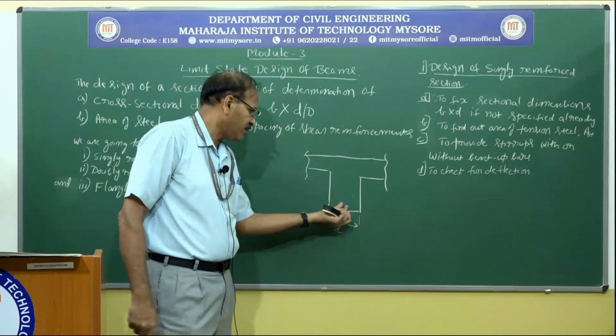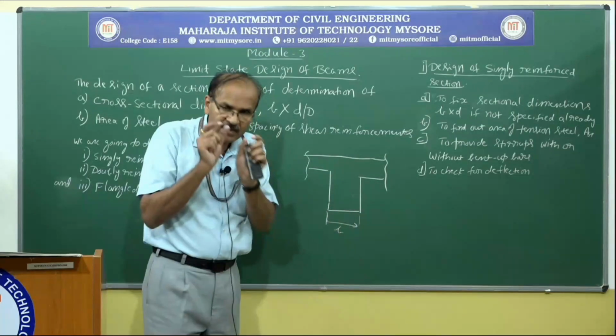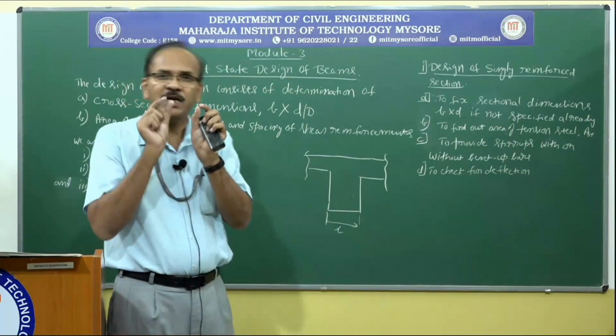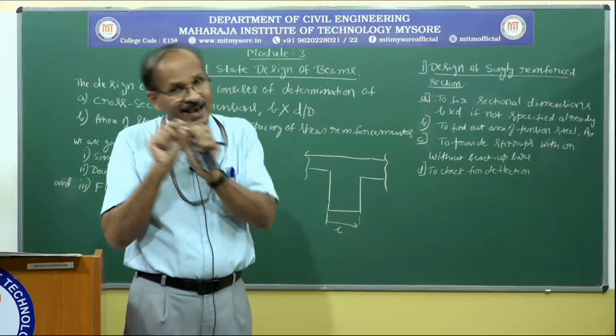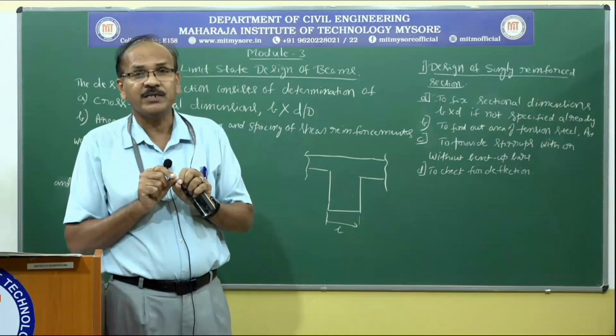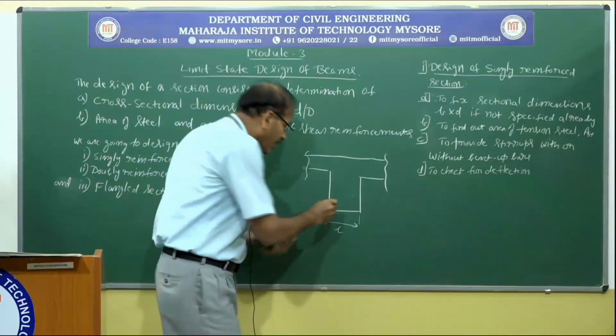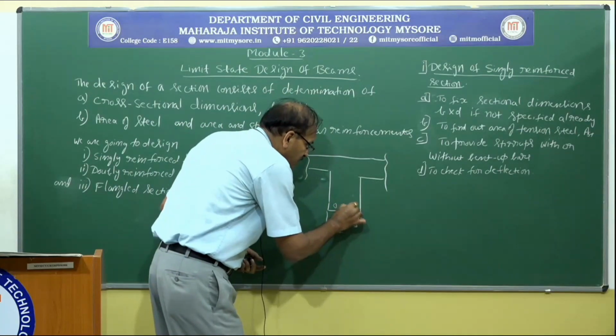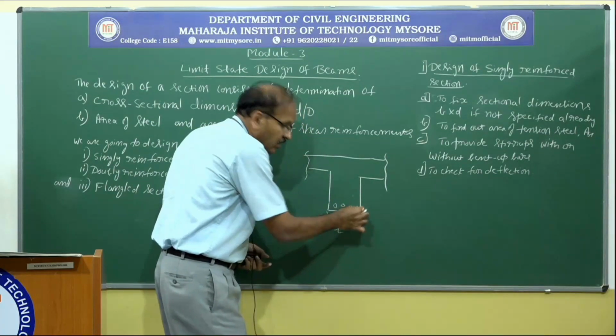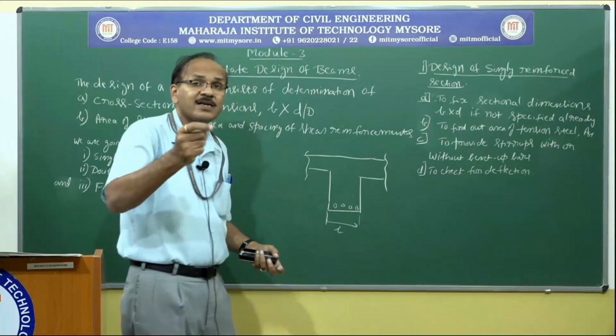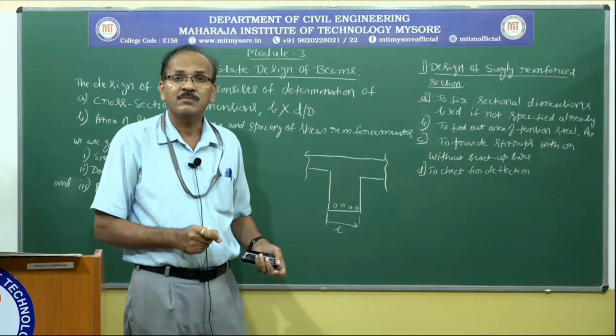We have to maintain certain spacing between reinforcements as per the codal recommendation, and also provide vertical spacing and horizontal spacing. Horizontal spacing is the side spacing.